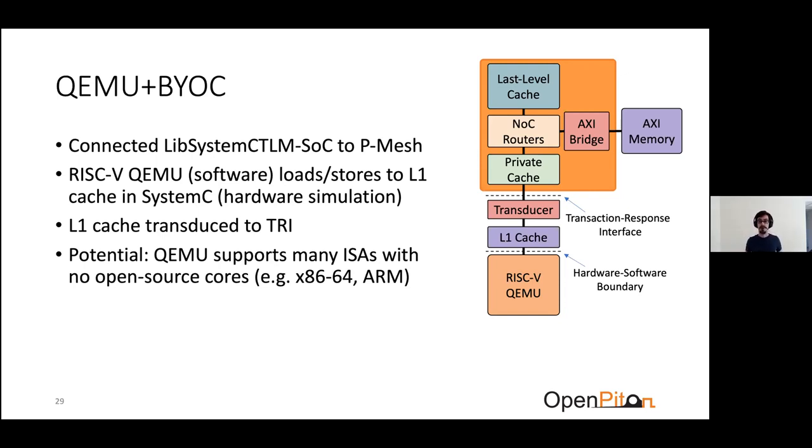And so the level of functionality that we got to with this was a few days. We were on a DARPA program together, and we had a hackathon for a few days. And so we actually built versions where they could do loads and stores into a cache that they had that was in SystemC. And then we just implemented a transducer to talk tree into BYOC. And so you could actually boot Linux in QEMU and then do loads and stores into a region that was mapped into BYOC. And so this could actually be pretty useful for you to try and build other interesting prototypes on top of.